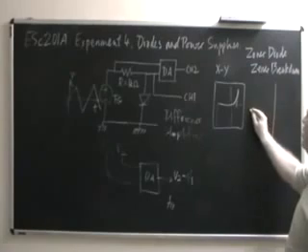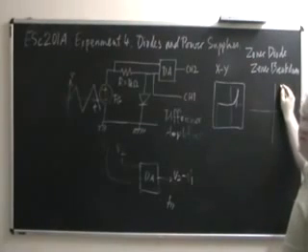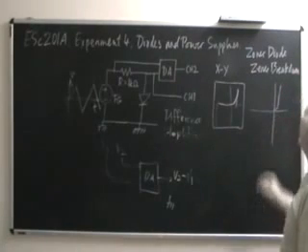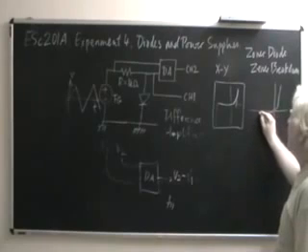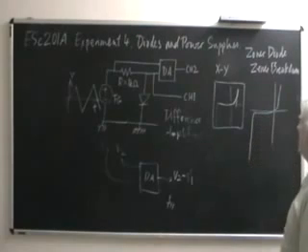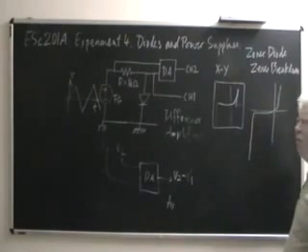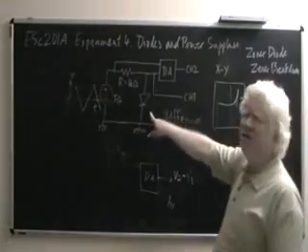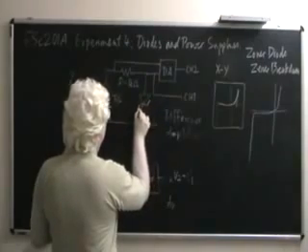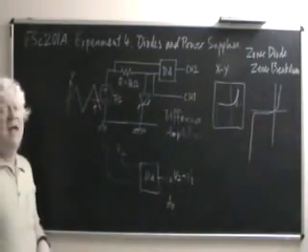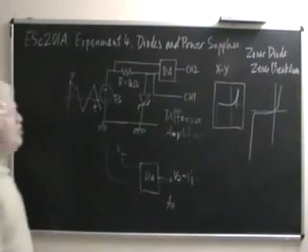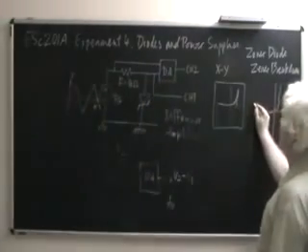Let me plot a Zener diode's characteristic for you. Not necessarily to scale, but indicative. This is the forward characteristic, a small reverse saturation current, and then a nearly vertical line. Now, if you replace this diode in the circuit by a Zener diode, whose symbol is this, and apply a signal here of sufficient amplitude to cross the Zener breakdown voltage Vz,